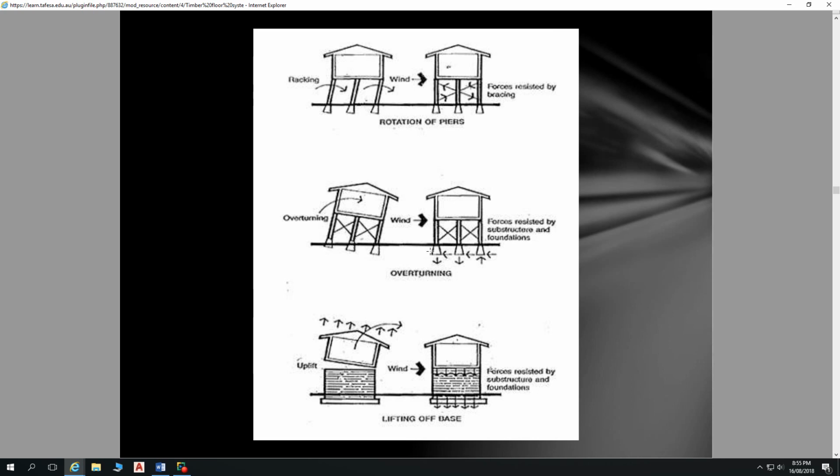Right, so you'd see it bust the concrete out between the bricks over the years. Aided also by the presence of salt. The concrete absorbs the salt water, and as it dries out, those salt crystals form and wedge off little bits of sand, so it slowly gets eaten away.